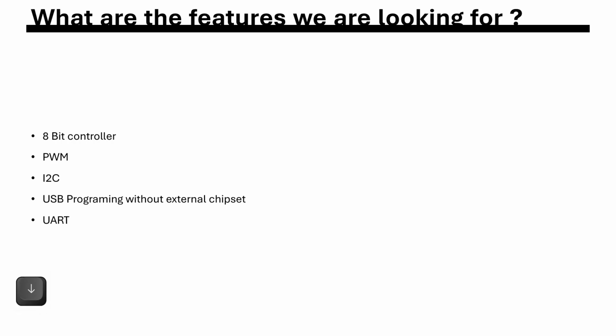So when we talk about a microcontroller, what are the features that we are looking for? Let's say I need a basic 8-bit microcontroller. That is the first feature. I require at least 8 bits. It should have pulse width modulation, I2C, USB programming without external chipset, UART or serial peripheral interface, timer.